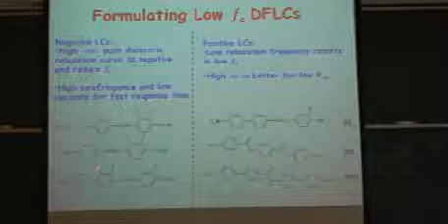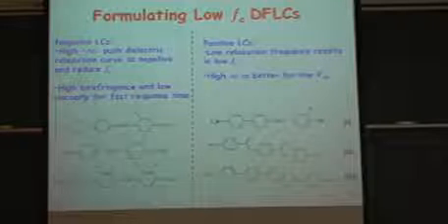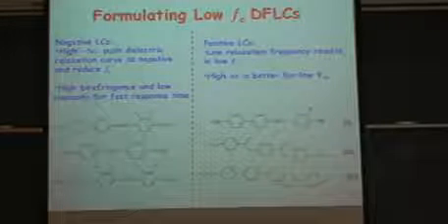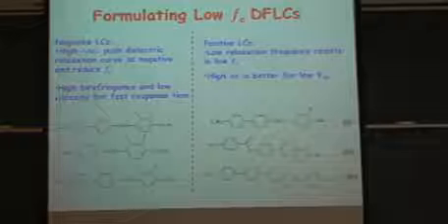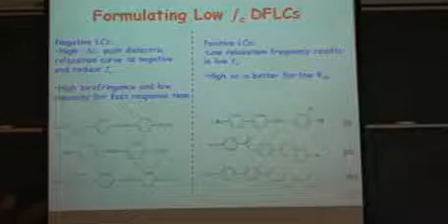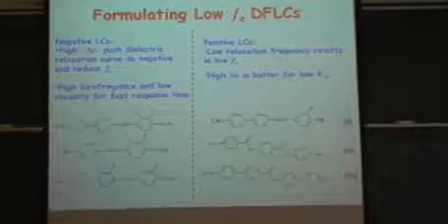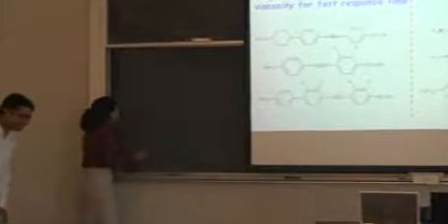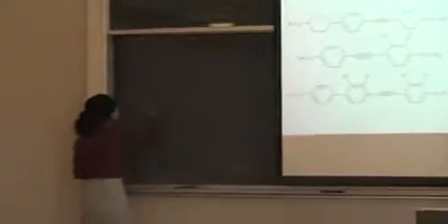Here, actually, it contributes to the cell gap. You remember, for example, we want to realize one pi phase change, and we have birefringence at 0.3. We can do a calculation.